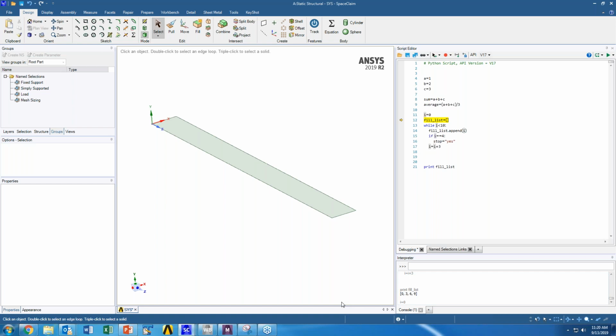So that's the debug mode. Those are the main features on this toolbar. You have your insight selection, your record button, your debug tool, and then your run tool. One thing to note is you can certainly always run in debug mode. However, as your script gets more and more complex, debug mode is inherently a slower way to execute your script. So if you want a fast execution, particularly for complex scripts, certainly run it in run mode instead.